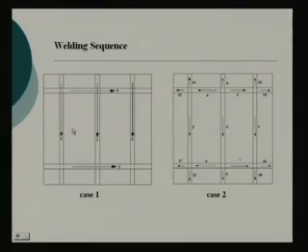That means rigidity against distortion is also increasing. A flat simple panel plate will much more easily buckle, but when it has the stiffness, it will not buckle that easily, because a lot of the load will be taken by the stiffener also, right. So that also has to be seen.